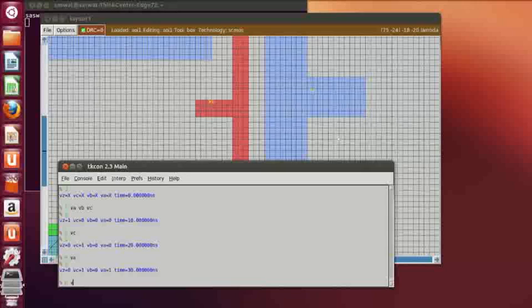Then high for VB, again that will be 0 because the AND output here is 1 and the OR output is 1, so again we get the invert. If I give low for VA and VC, then I'll get 1. Why? Sorry, the AND output is 0, the OR output is 0, so the invert will be 1.